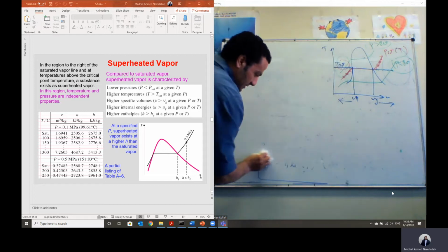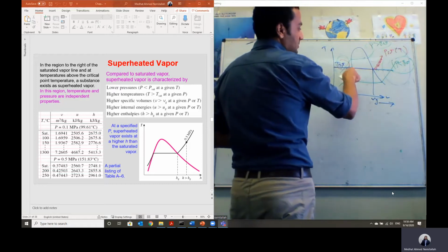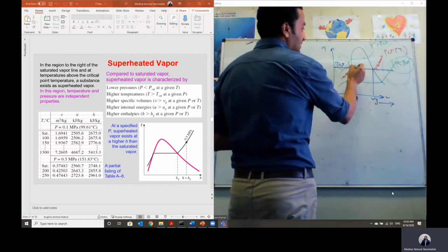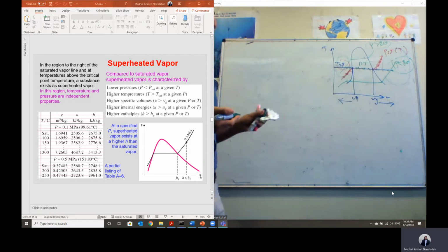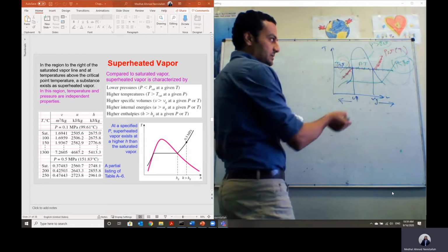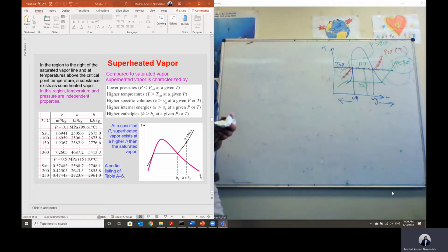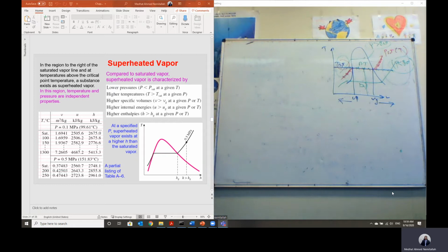We said for steam, in case of saturated mixture, all points between saturated liquid and saturated vapor have the same pressure and same temperature. So in this case, we cannot say pressure and temperature are independent in case of saturated mixture, because all points have the same pressure and same temperature. We cannot make a difference in this case. And for this region, the value of the quality X should be given. Okay. So our target is to calculate the properties, given two independent and intensive properties.